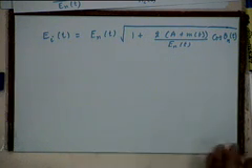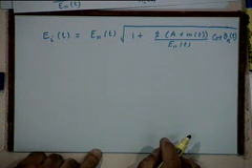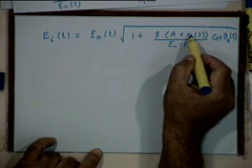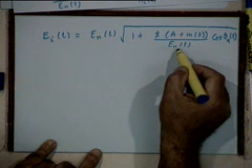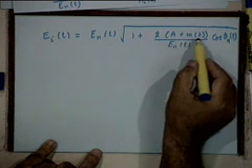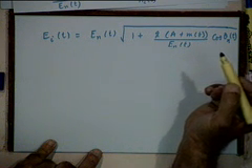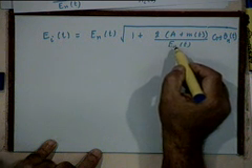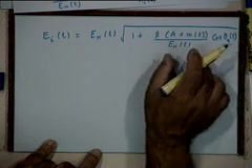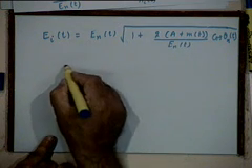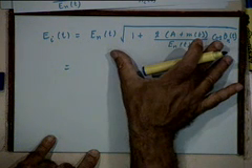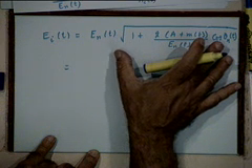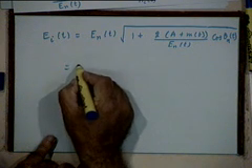Okay. So, that is the expression that we have for the instantaneous envelope. We once again use the approximation that A plus Mt is much less than Ent. Ent is a noise amplitude, right. A plus Mt is a carrier plus signal amplitude, which we are assuming to be much smaller than the noise amplitude, right. So, once again if we use that approximation, we can carry out a binomial expansion of this square root, right, and retain only the first term.